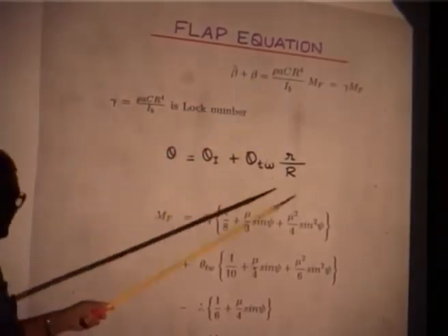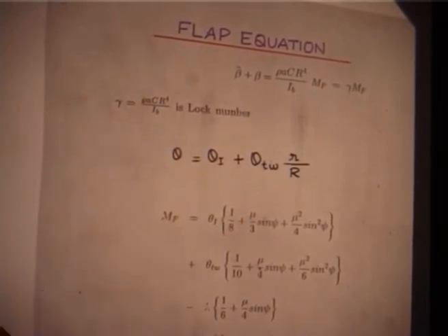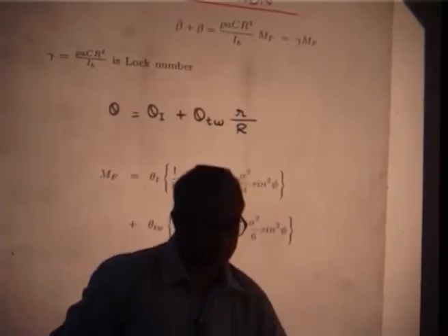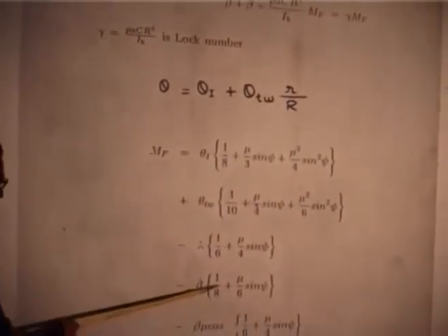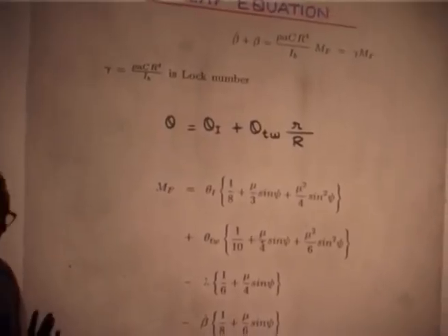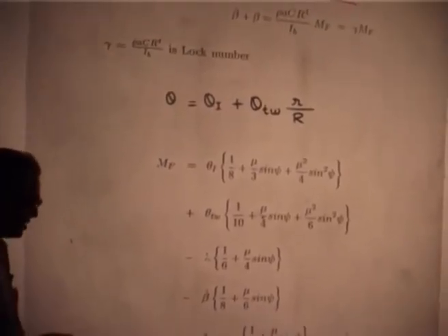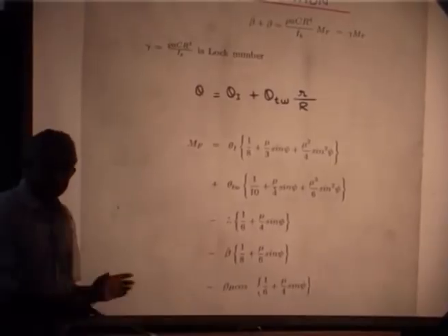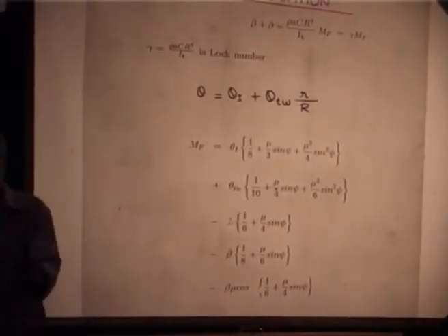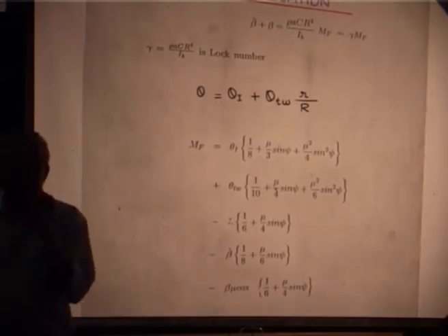The damping term is on the right side, which I can transfer to the left side. Please understand, the damping term which is here can come back here. But in forward flight you also have an additional stiffness term. That is why we do not write it immediately as some frequency.